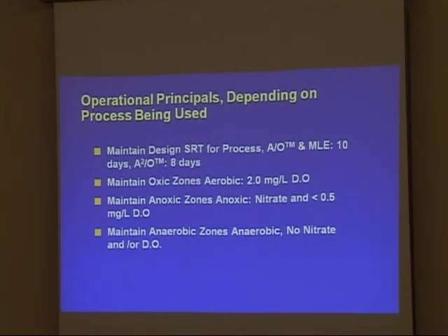So SRT for the AO and MLE is 10 days, and the A squared O is 8 days. This is an aerobic SRT, so this is the solids retention time measured based on the aerobic volumes.